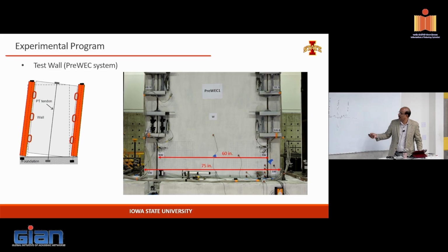It could be a steel plate welded on one side, like a cantilever piece welded. In this case, we use steel columns, so it's welded to the steel column. So it will prevent the plate from buckling outward, and they will deform in the in-plane direction. I mean, there are not significant forces in each one of them, and the out-of-plane force is also small. So restraining them is not that difficult.